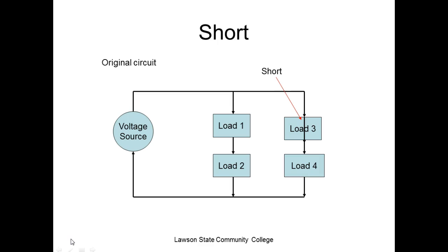Now, according to Kirchhoff's voltage law, the sum of the voltage drops in a series circuit has to be equal to the applied voltage. So if we have a short, how much voltage does the short drop? None. It's like replacing the load with a piece of wire.